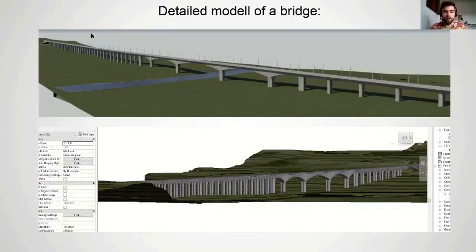So here, they're actually modeled in Dynamo and then imported in Revit. And again, it was automated. Here, it was not a single push of a button, but still, we were getting the data from Civil 3D, directly pushing that into Dynamo. So these models were really detailed, they had all the correct slopes in the lanes of the bridge to make it work. And then the piers, the supports, were also placed with Dynamo to the correct heights, so they match the topography and the underneath surface of the superstructure.